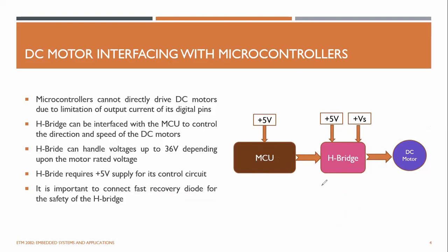In the market, you can just buy H-bridge drivers. Even for Arduino, there are some H-bridge shields. So you just need to couple the shields to the motor and to the Arduino. But if you use an H-bridge type IC, you would have to add some external components and build your own H-bridge. But there are some built-in H-bridge shields you can buy from the market. That is easier than buying an IC and building an H-bridge by yourself. All right.